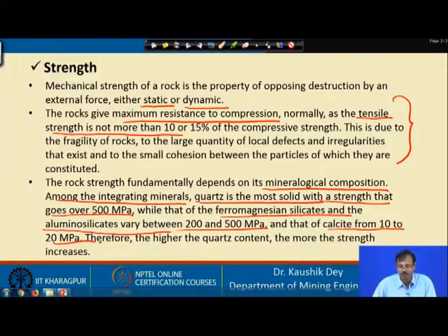That means, from very soft to very strong rock conditions. Basically that measures the integrity of the rock. Rock strength also depends on the mineralogy, not only the mineralogical composition, but also the formation. In general you will find the rock formed under volcanic eruptions, under high temperature and pressure, shows higher rock strength than rock formed by sedimentation or similar processes.